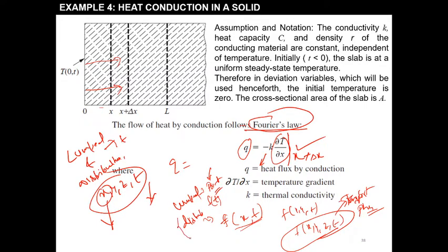When the distributed parametric model of the problem comes into the picture, then you can see that when the model is developed with the help of the distributed parametric model, the model is based on the partial differential equation, PDE. Why PDE? Because it is del by dt, and the temperature not only depends on time, the temperature depends on the x value, the dimension, also.